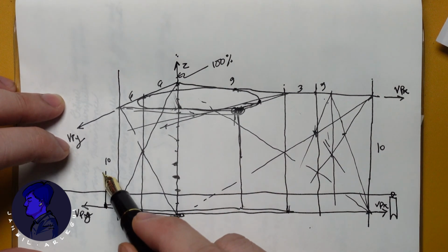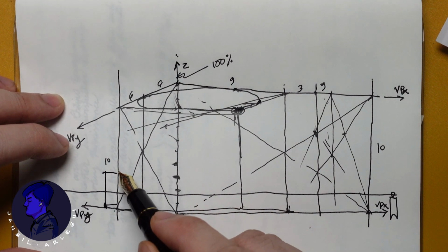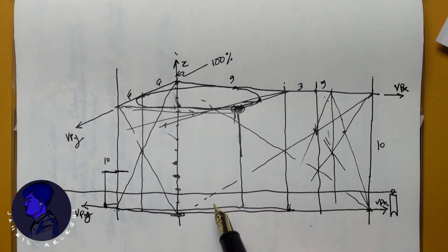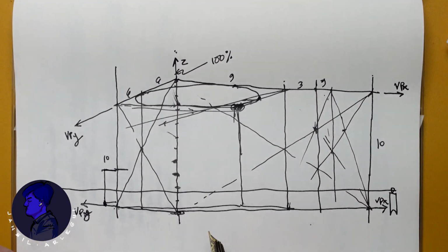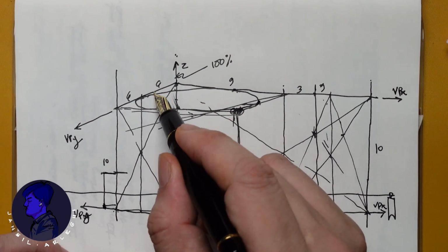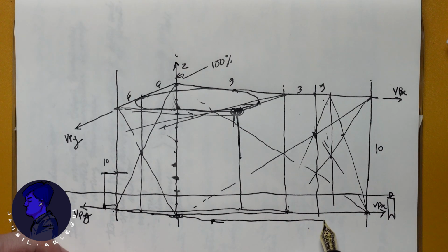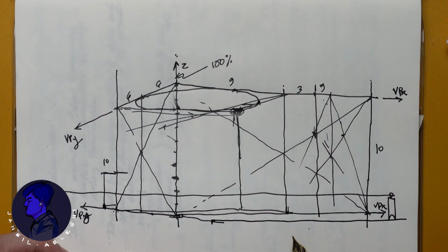I would have a firewall, something like there, and the neighboring wall going like that. Then here, I have a 5-meter frontage, roughly about 4 meters from here. So I take again from this side, 4 meters is somewhere approximate there. I want to replicate that dimension going through here, extending that. Okay, so this is slightly going to be here, and then that would be where my property line or where the sidewalk will start.